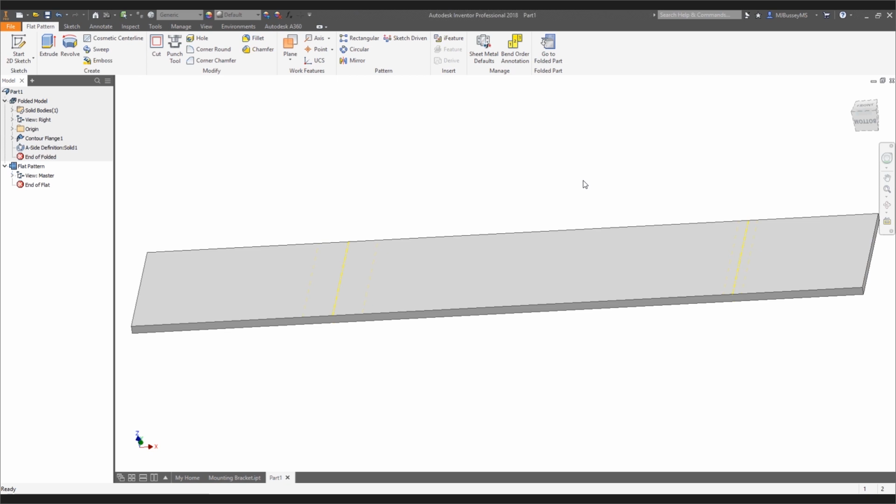So if you're seeing that kind of variability in your manufacturing process, and you need to make sure you are calculating a flat pattern that accounts for it, you basically have to go back to basics, just like the guys at Lockheed did many, many moons ago. You've got to run some experiments, take some measurements. Once you have those measurements, plug them into Inventor as unfold rules, and have basically engineering design methodologies saying, if you're creating this type of feature, this is the unfold rule you have to use in this particular case. I wish it was easier and simpler than that, I really do, but that really is the reality of how it has to work.